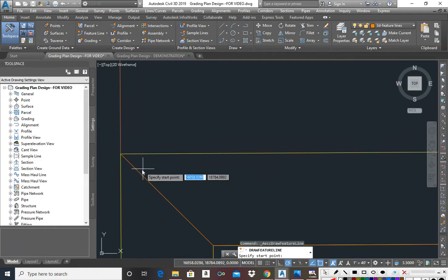You'll notice that if I'm hovering over here and find the endpoint of the feature line, if I hover over here, you'll find the endpoint of the yellow line, which is the curve at the 0 elevation. I need to make sure I'm working with the z's, which are somewhere in the 3,800 foot range. So I can either do this, or I can go over here and hit tab a couple of times so that it cycles through all the different options. However you want to do that, and it finds different elevations. This one's finding the one at the bottom, which is not the correct one. You see it over here that it was highlighting this one.